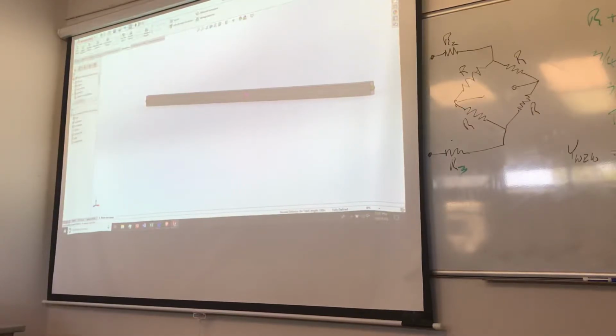Okay. So now we're going to constrain it, right? And this one we can do fixed geometry, and amazingly enough, we really can come over here to the end and say I'm going to pick on a joint, and just pick on that one, and it's just done. It's fixed as it can possibly be.